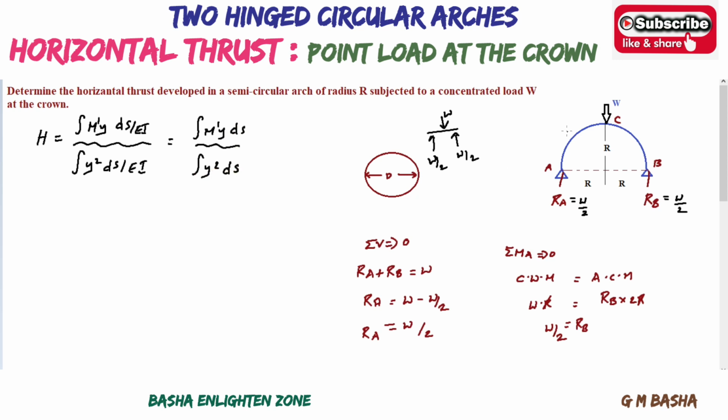Here we have to consider a point P (x, y). First resolve the numerator, that is M dash y ds. What is this M dash? M dash is the moment on the arch. For that purpose we consider one point P (x, y), exactly a section XX at a distance of x from A. So this is the section XX, with distance y and distance x, at a distance of x from A.